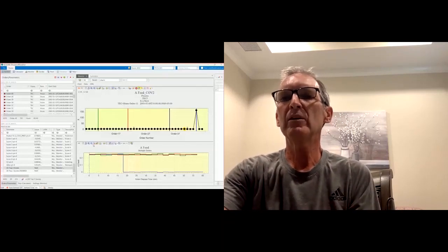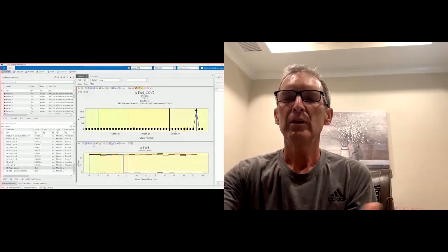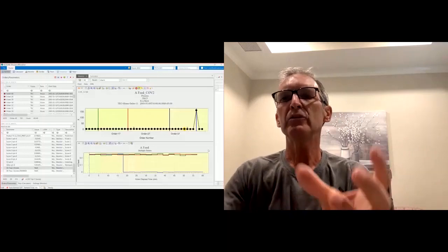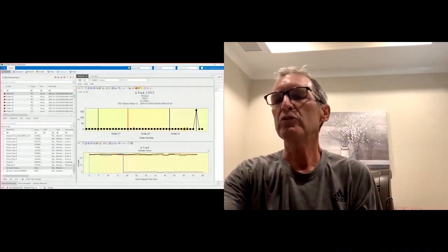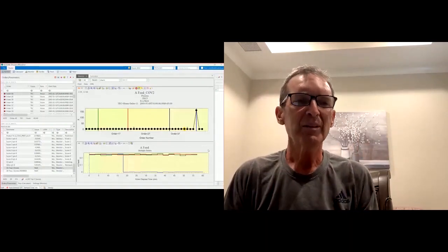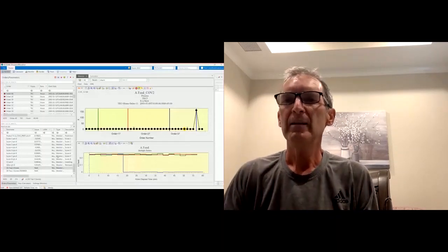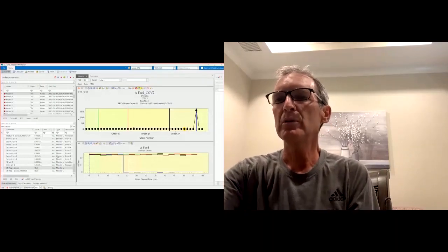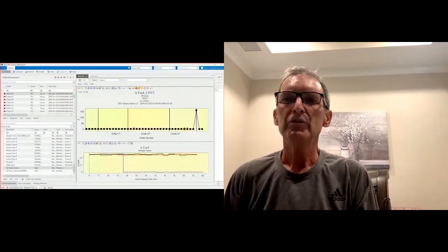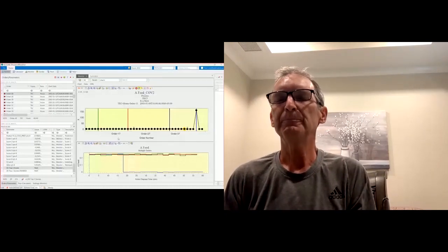The main thing we're trying to get across here is that you can take a lot of data. There are 40 batches with 100 different parameters each. Each batch takes about an hour to produce. And you're able to boil that down to an overview screen with control charts that are already set up. This basically creates the control charts for you, so it takes very little work to get a quick overview of what is happening with your process. And when something does show up as abnormal, you can just click on the parameter and it'll show you the contributing factors, so you can quickly analyze what's happening and know what to work on to make things better.